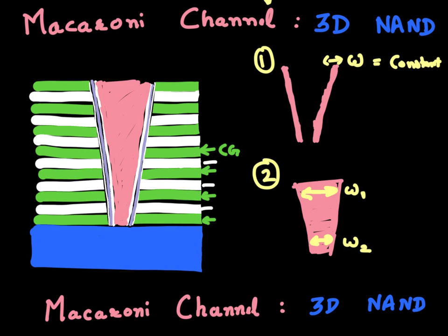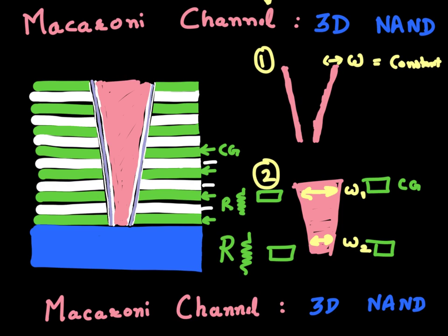So if I make a stack using this second option where I have a solid plug, I see that the transistors which are at the top would see a much wider channel, and this transistor would have a much smaller resistivity, while the transistor at the bottom would see a narrower channel and would have a more resistive path for current flow.